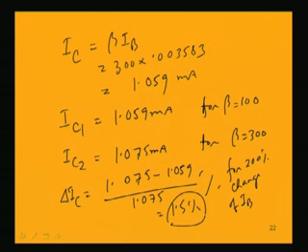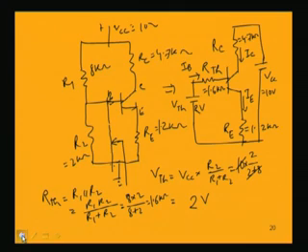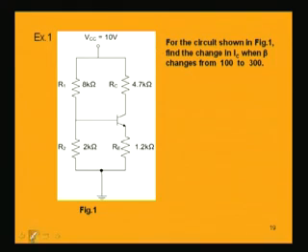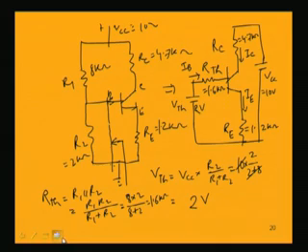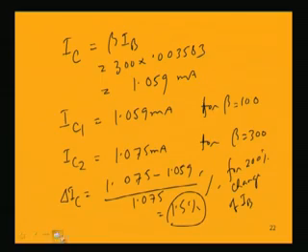That is actually possible because in this design, if we cross check the values of R Thevenin and beta plus 1 into RE, the design specification to be met is that R Thevenin should be very much less than beta plus 1 RE. It must be there, because otherwise you would not have got such a marginal increment of IC. So, what is beta plus 1 into RE?